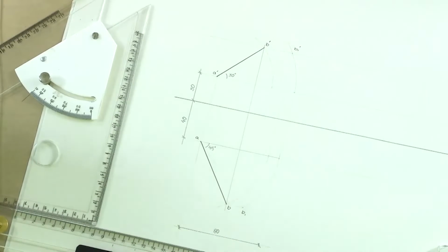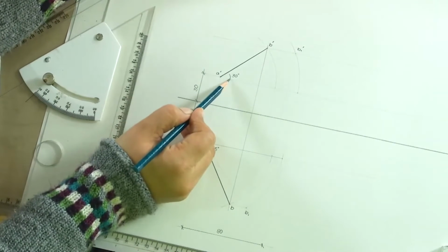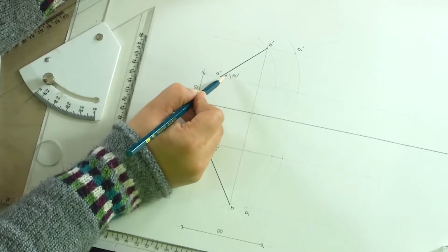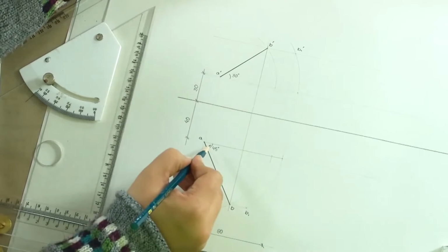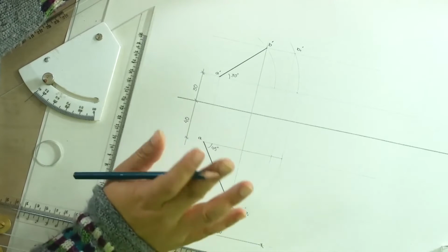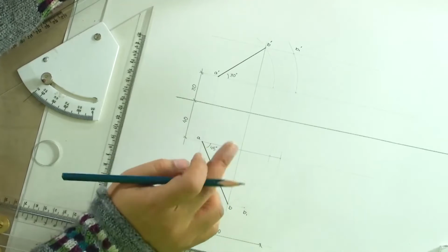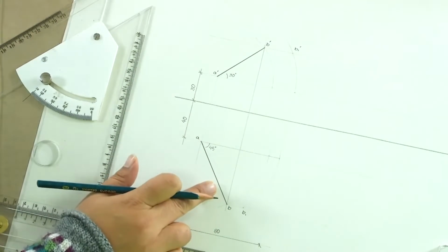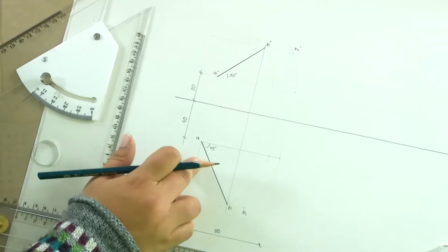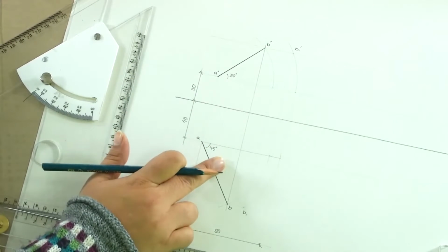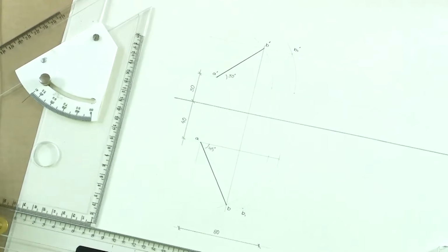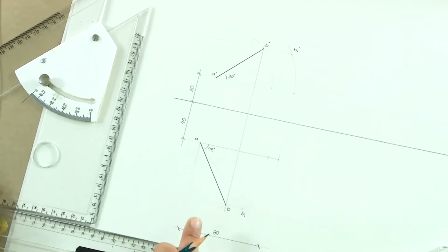Now, you can see very clearly that the actual angle of 30 degree is not the same angle that we see in the final projection. This angle has changed, and similarly, this angle has changed from 45 to something else. We cannot determine that angle before we draw it. However, once we have drawn it, we can determine it or we can measure it. But there is no way to calculate it unless we do a detailed mathematical calculation. So, this is how we would be drawing the doubly inclined lines.